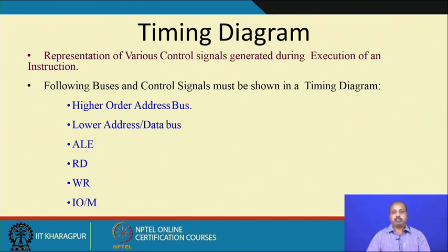Here also the same thing: now we know the 8085 architecture, and for executing instructions we need to control a number of control signals, and the 8085 decoder and sequencer does exactly this operation. So, we will look into some of the instructions and how they are executed over a number of T states.